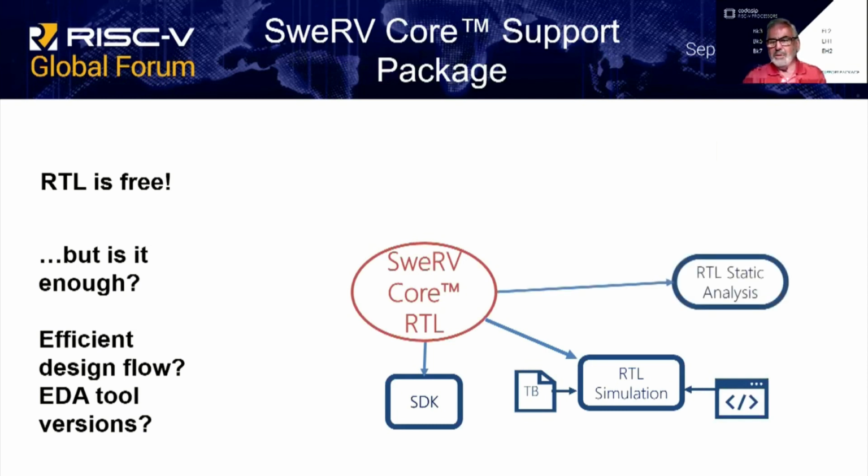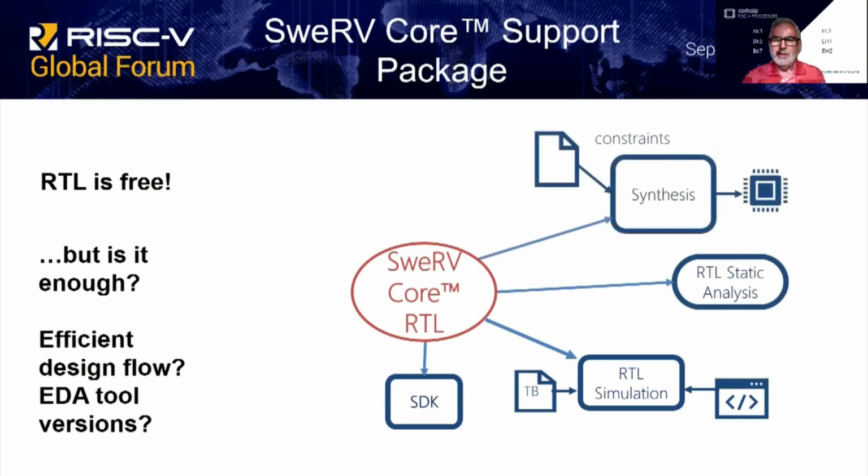You may want to do static analysis on your RTL, such as linting. You'll certainly want to synthesize the design with suitable design constraints. And once you've synthesized the design, you want to take the output and check that it is equivalent to the original RTL.